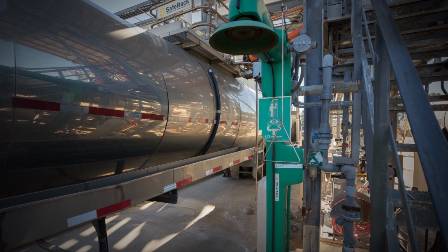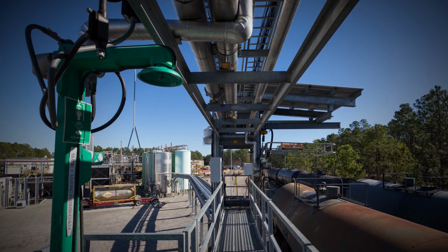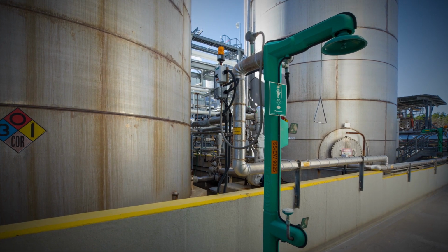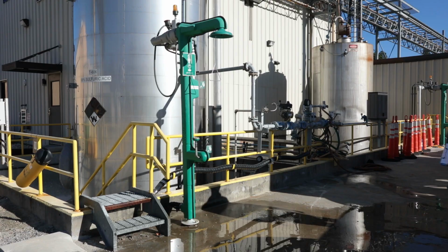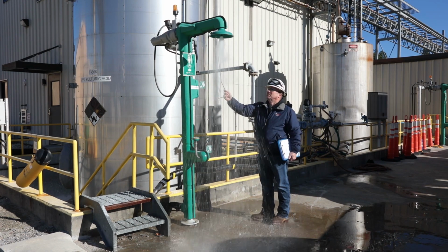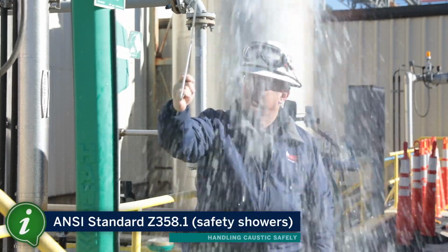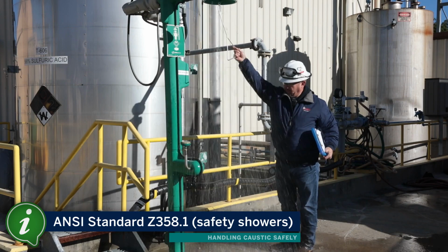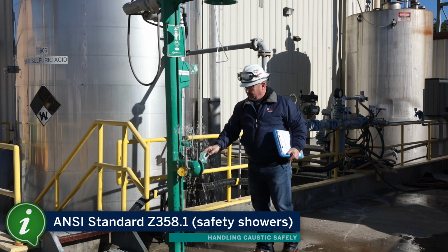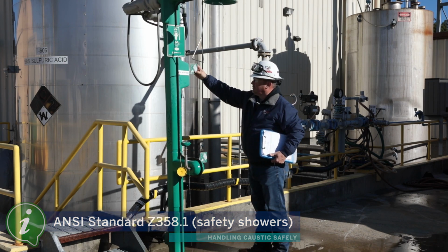Safety showers and eye wash fountains that are readily available, clearly marked and operational in all areas where caustic is being handled, will provide for quick irrigation of skin or eyes exposed to caustic. Safety showers and eye wash fountains should be checked for proper operation before beginning caustic handling activities. Users should also consult the latest ANSI standard Z358.1, which outlines additional criteria in the safe use of safety showers. Topics covered include safe design, placement, water temperature, and inspection procedures.